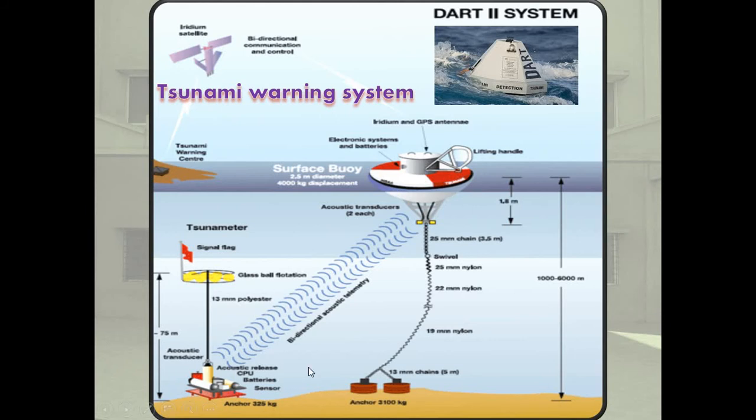Generating and updating the high resolution database on bathymetry, coastal topography, coastal land use, coastal vulnerability, as well as historic database on tsunami and storm surges to prepare and update storm surge and tsunami hazard maps, on 1:5000 scale for coastal areas within 1 to 3 km in general and for 10 to 25 km at selected areas near the coastal water bodies.